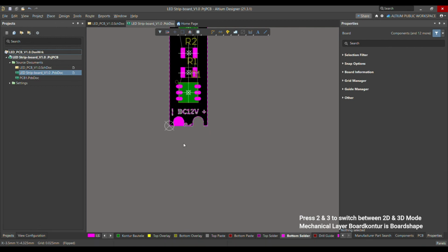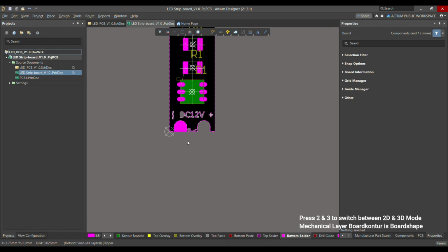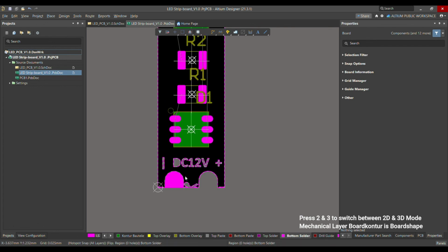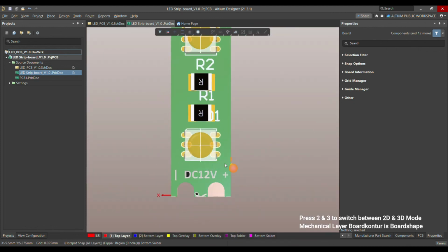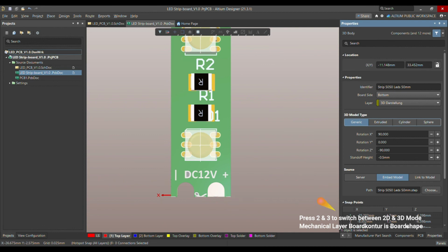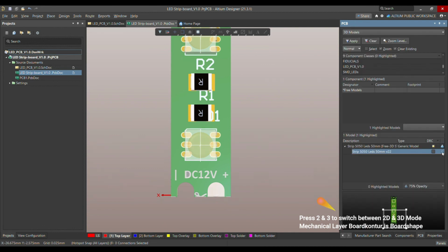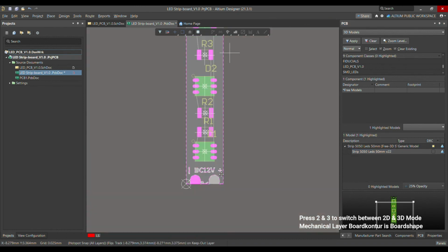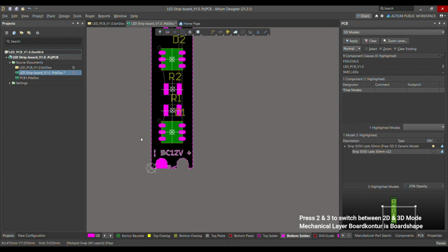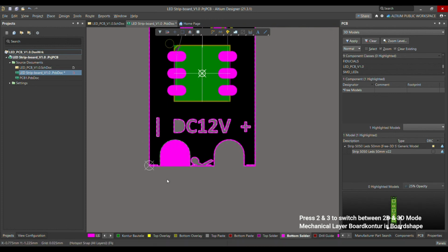So yeah, that's how you can transfer the 3D body or 3D portions. Just let me check it here. So now it's available. That's how you can transfer. I mean, if you have multiple parts in your 3D STEP data, then that's how you can select individually and transfer it from 3D to 2D.